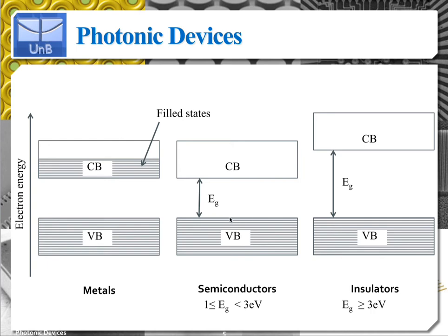Okay, so some electrons at room temperature can still overcome this band gap, and therefore at room temperature you will have a few electrons in the conduction band. And if they are able to overcome the band gap due to temperature, essentially vibrational energy, and they're up here, they can access these next available states as easily as electrons in metals can.